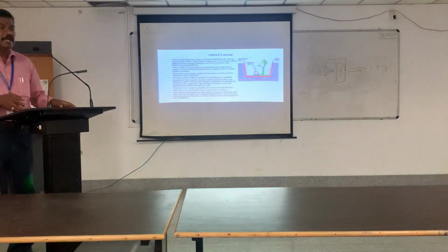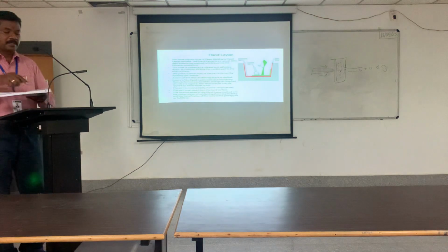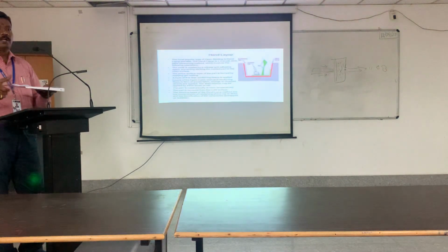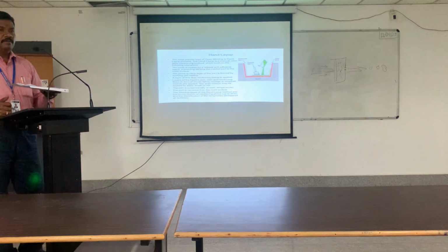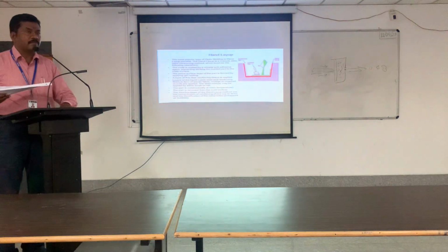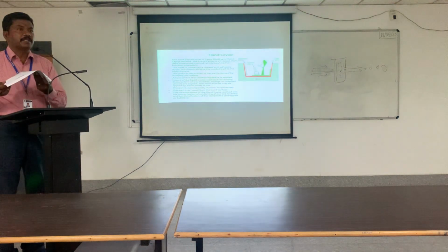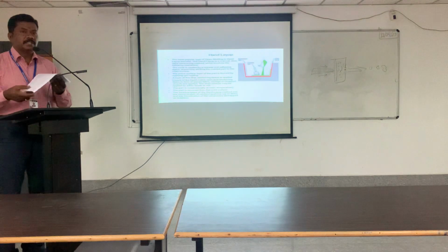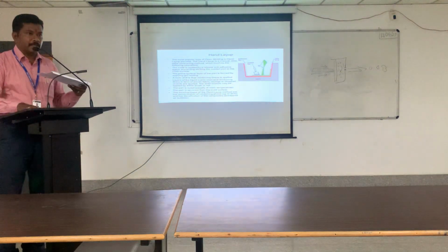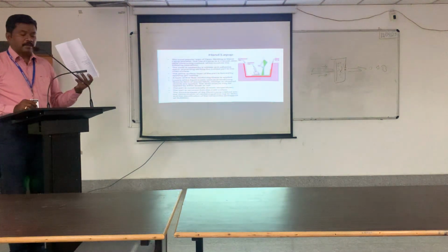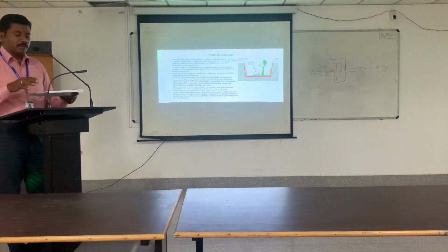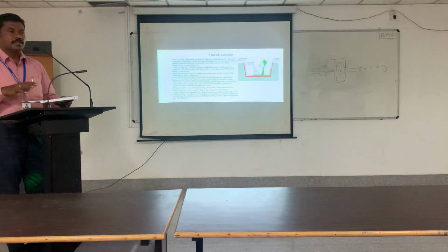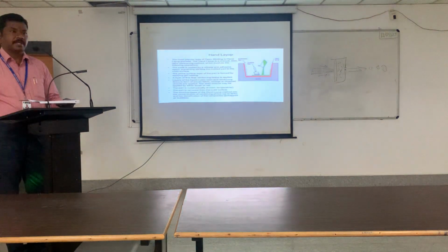If I want a plate-like structure made, of A4 paper size, a composite plate of 10 mm thick, for this I should select a flat plate. If I want a curved component, I should have a plate with curvature. Since I want a flat type, a flat table should be taken, and on top of it the reinforcement and the matrix material are to be placed. Once it has been cured, the plate can be taken away.